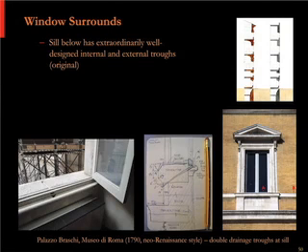But at point A, the glass is impervious, so every drop of water that hits that window is going to wind up right at that sill. So between all that water being kind of funneled right to the sill, between the wall being very low at the sill, as you see in the sections at the right and in that photo from Ciciliano, something has to happen in the sill. What sort of magic happens? And then that also makes it no surprise that that area below the sill is stone, whereas to the right that's brick. You're funneling a lot more water to that point. They use the more durable stone to get the water from A down to that next band course where it's going to be shed from the facade.